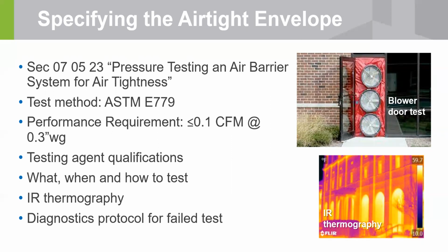In that section were test agent qualifications, what, when, and how to test it. There was also called for some IR thermography to look at the thermal efficiency and to locate any air leaks, especially important if the building would fail that test, and a diagnostics protocol for a failed test.